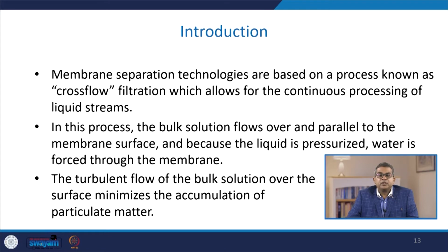Now, let us have an introduction to the various microfiltration tools. Membrane separation technologies are based on a process known as cross-flow filtration, which allows the continuous processing of liquid streams. In this process, the bulk solution flows over and parallel to the membrane surface, and because the liquid is pressurized, water is forced through the membrane. The turbulent flow of the bulk solution over the surface minimizes the accumulation of particulate matter.